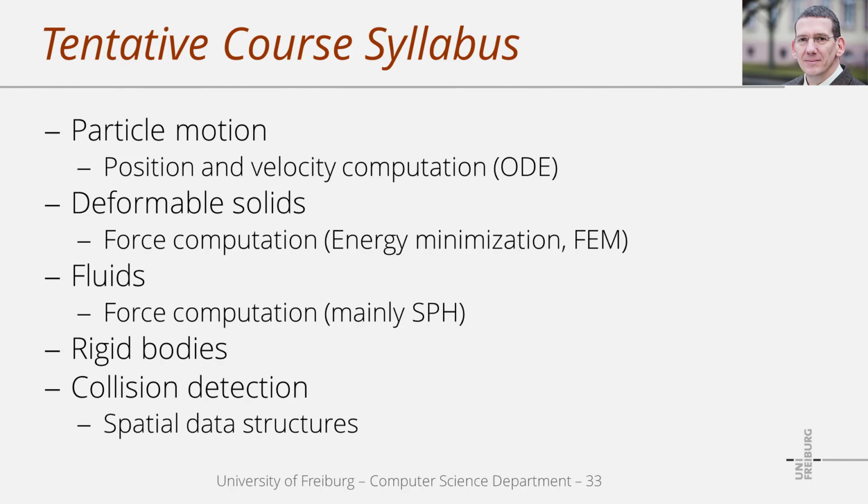And here we will look into so-called discretization schemes, namely SPH, to approximately compute the force terms from the Navier-Stokes equation with simple sums over adjacent particles. As our final material, we look into the simulation of rigid bodies, and after that I will present some spatial data structures that are being used to detect collisions.